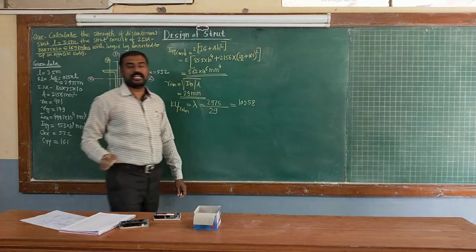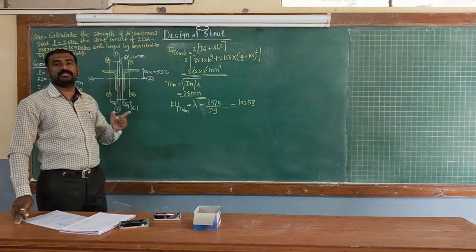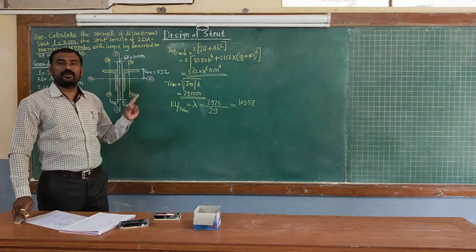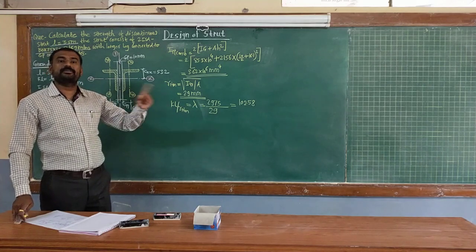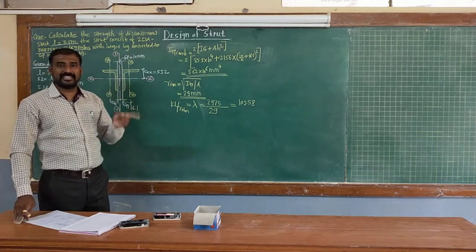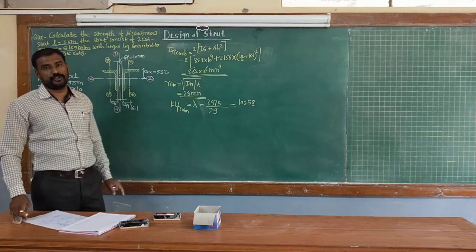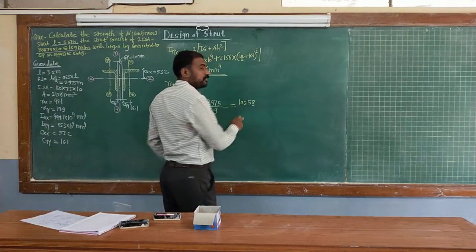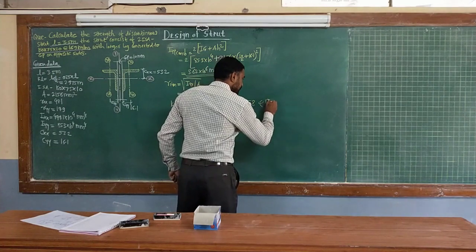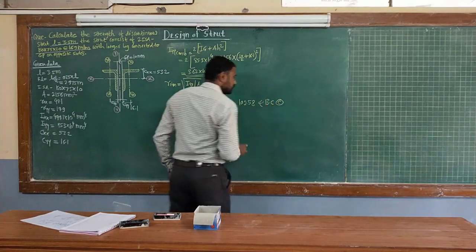As we have seen, there are buckling classes A, B, C, D, and according to table, angle sections always come under category C, correct? So referring table 9C for design compressive stress, given on page number 42, and 102.58 is the lambda value with buckling class C.